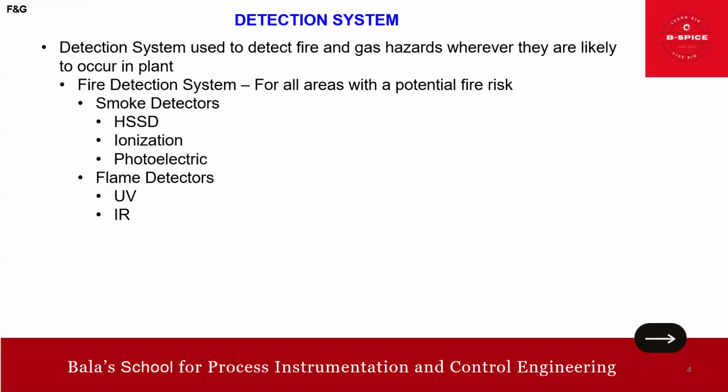Talking about the key features, of course, detection of IR radiation. Basically, it monitors specific IR wavelengths emitted by flames, typically in the range of 4.3 micrometer, which is the characteristic of hydrocarbon fires. And flicker detection. IR flame detectors often rely on the flickering motion of flame to distinguish between actual fire and other sources of radiation. That is also one of the features. Then false alarm reduction. Advanced models have algorithms to minimize false alarms. Application as usual: industrial safety in oil and gas, power generation and aerospace, friends.